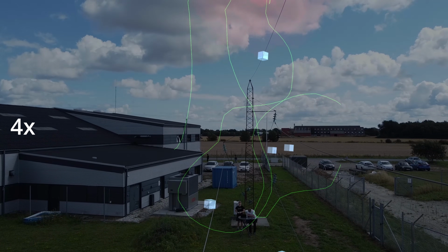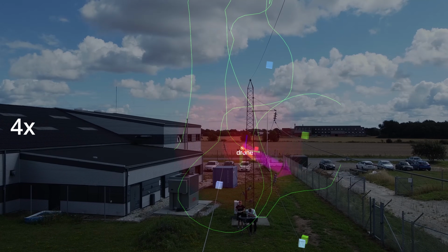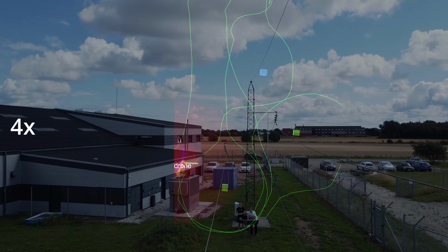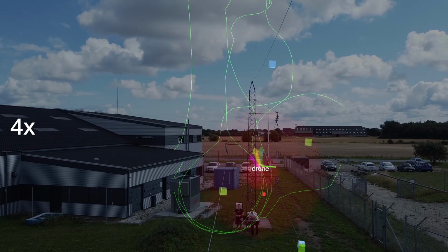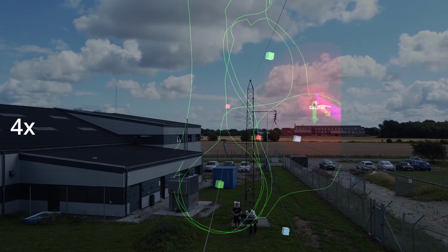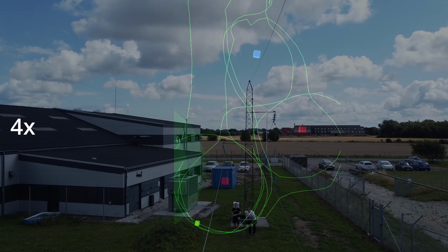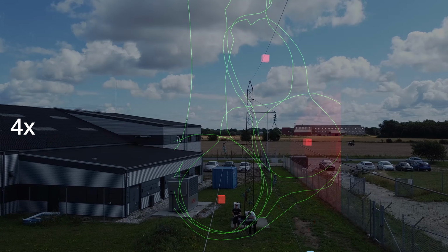The summation of all tangents is displayed as the magenta arrow, and the corrected output velocity is visualized as the yellow arrow. The red arrow indicates the current velocity of the UAV, and the green arrow shows the desired input velocity from the user, which could be either an autonomous system or a manual pilot. The inner red sphere is the safety sphere. Whenever detections are made inside of it, the UAV immediately rejects itself away from that detection.